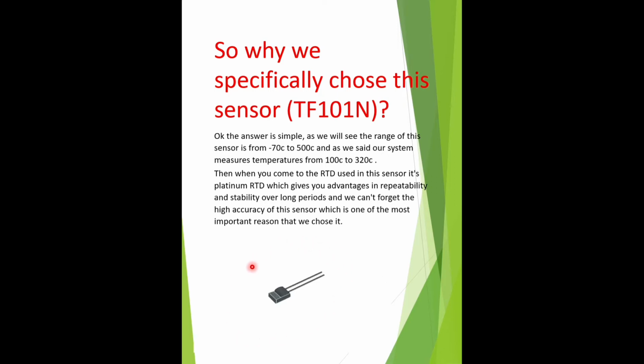We used the TF101N sensor, but why did we specifically choose this sensor? Simply, not only does it cover the range we need, but it also uses platinum RTD, which gives better repeatability and stability over long periods. And we cannot forget the high accuracy this sensor provides.